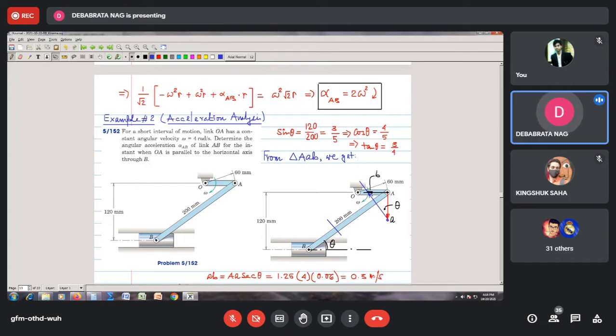So you see that I take this geometry once again. As I told you, for doing the acceleration analysis, you need to do the velocity analysis first. Velocity analysis should be your cup of tea, because we have solved so many thus far. Take the pole A. Since point A has velocity in this direction, it must have the tangential velocity in this direction. So you draw the line AA first, and then the relative velocity of B with respect to A